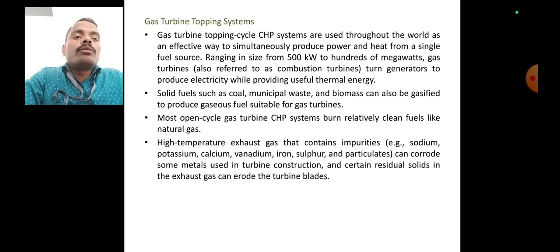A gas turbine based power plant is the simplest plant. It can start and stop in a short interval of time, whereas a coal based, steam generation power plant may take 2 to 3 days to start and stop. We can start quickly, which is an advantage for our industry when using a small capacity gas turbine power plant.